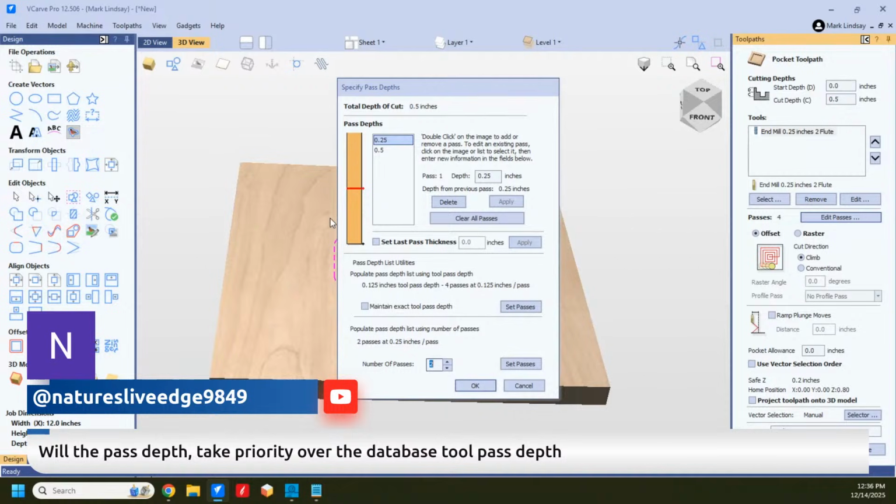Also known as it's actually bending slightly. Now, most solid carbide bits, while carbide is brittle and it's easy to shear off, if you've ever broken a bit, you know this, it will still bend. Carbide is brittle, but it will still bend, and that's what tool deflection is.